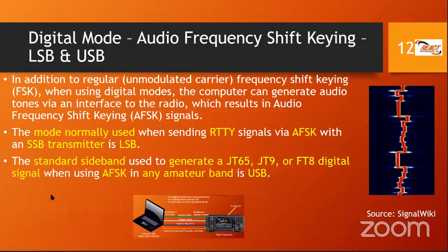All right, we just talked about FSK, frequency shift keying. But we can also use a computer to send modulated audio to the transceiver. When we do that, it is called AFSK, or audio frequency shift keying. So we can do RTTY using FSK, and we can also do RTTY using AFSK.